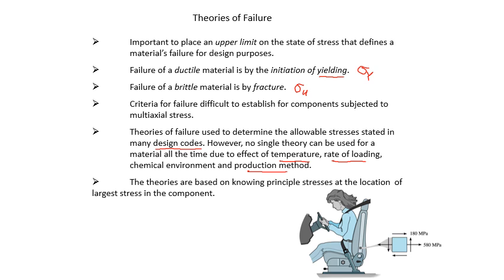Therefore, in using theories of failure, although we say we know the material, we have to check whether in its use there is a significant temperature change, whether there is a very high rate of loading, impact, things like that, whether there is a chemical environment where it is being used, and also the production method.